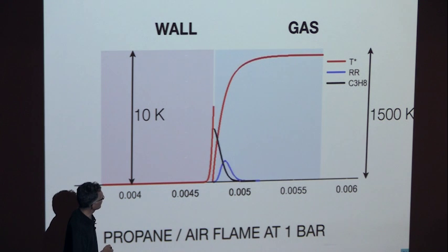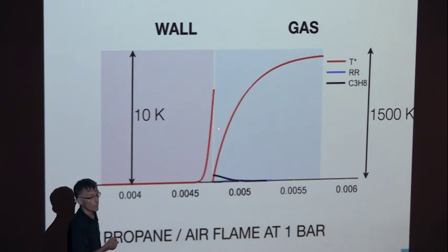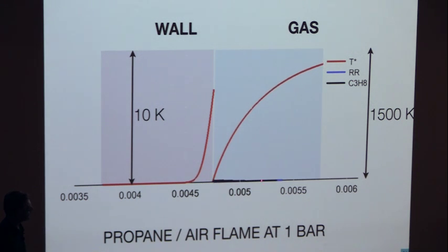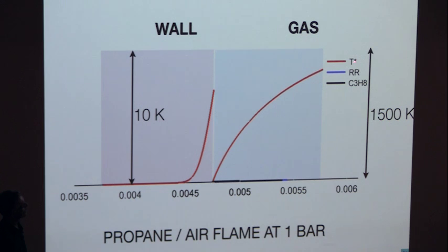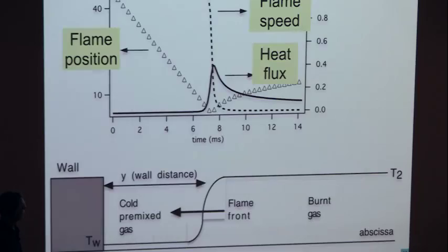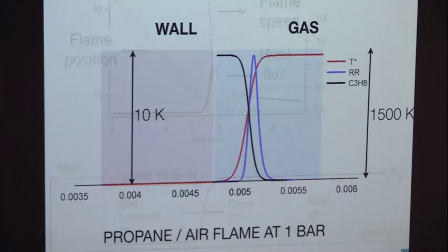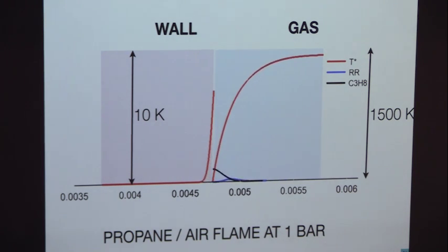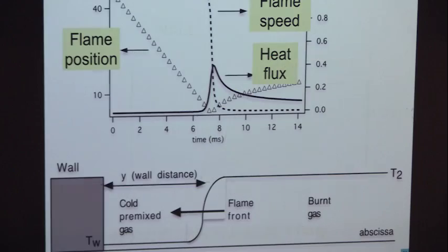Look at the blue line. Whoop. It never reached the wall, okay? It died before. And after it died, now we only have a heat transfer problem. Since the wall is cold, it has to cool down the gases in front of it. There's no flow. Actually, there is an induced flow here, but nothing's moving. This is head-on quenching, no flow rate for the moment.